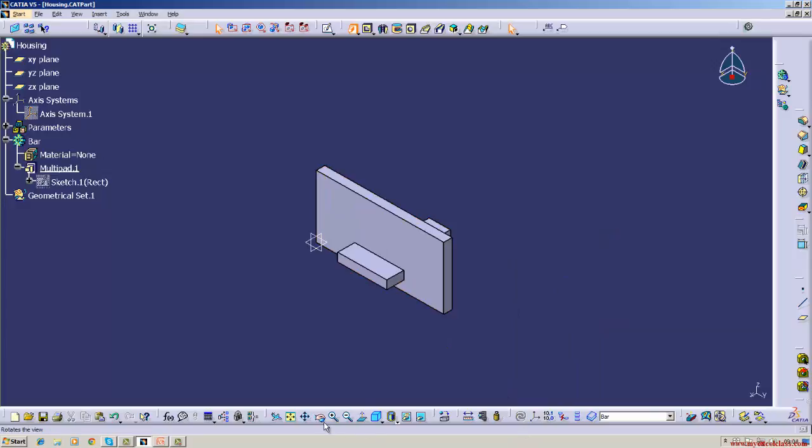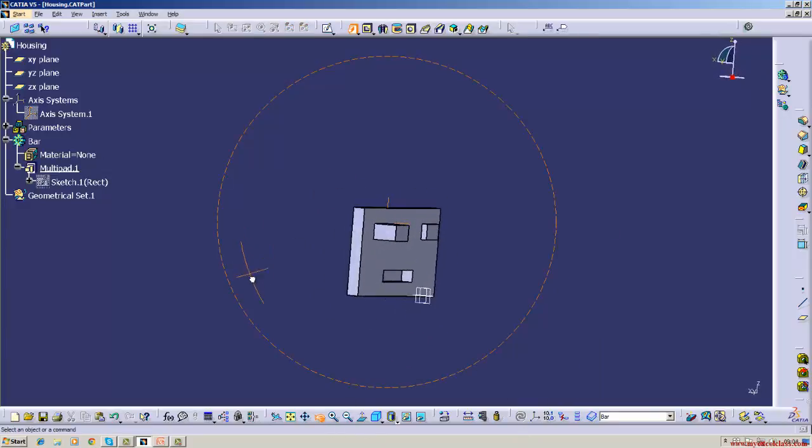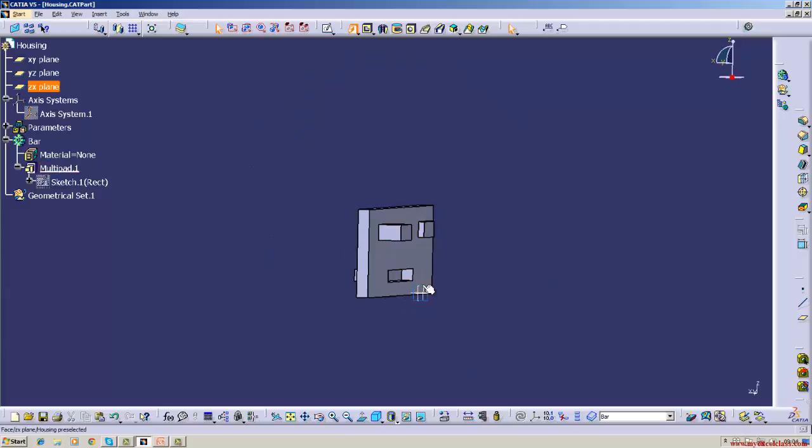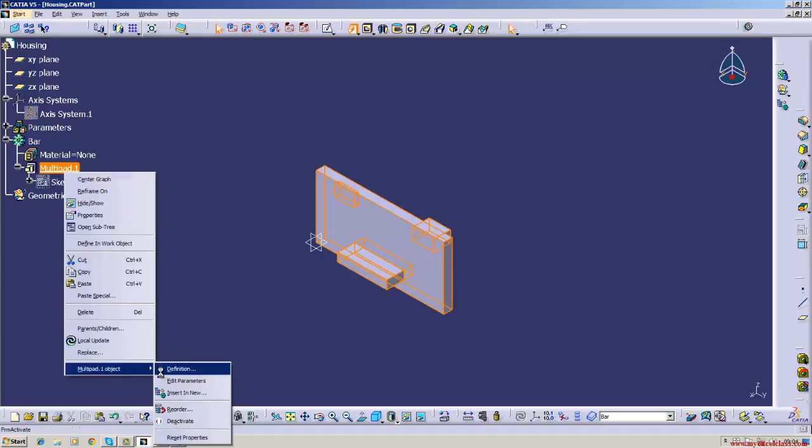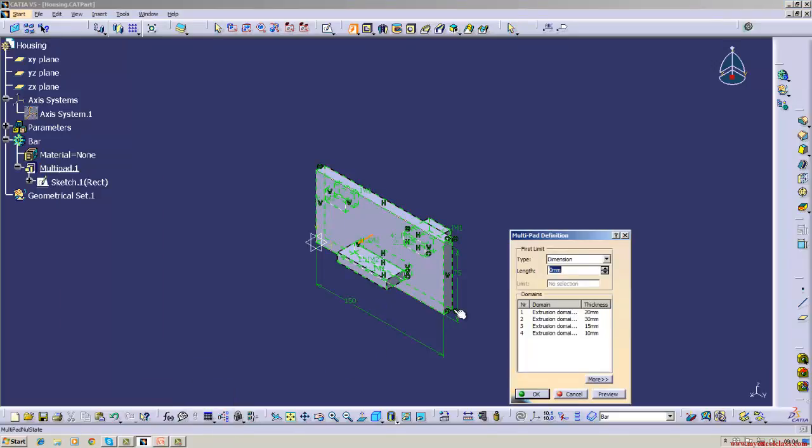2 pads inside, 2 pads outside. See. And here you got a hollow because this has projected in the opposite direction. In order to make this filled up, what you have to do is select this one, and add a value to that.